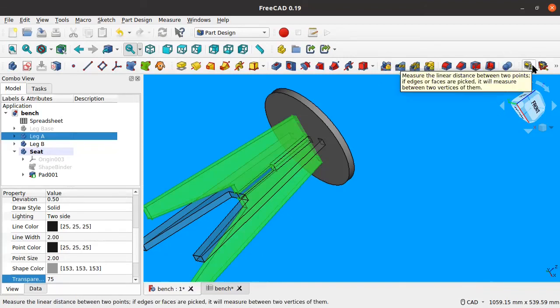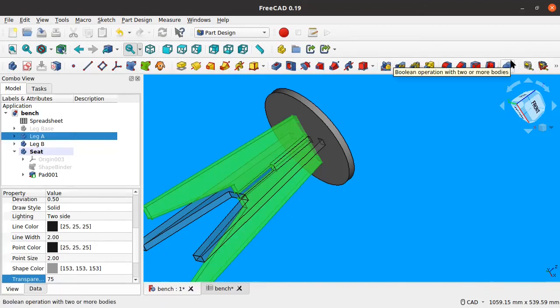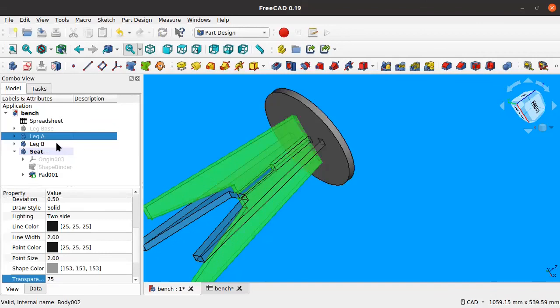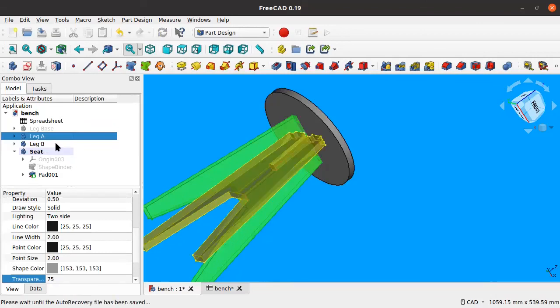You can also combine multiple, like make a more complicated Boolean operation, but usually it happens between 2 or more elements. Boolean is basically always happening with 2, but then probably there are abstractions on top of the feature in FreeCAD so that you can do subtractions and additions with multiple objects. And then the Boolean operations just happen one after another with each pair of objects.